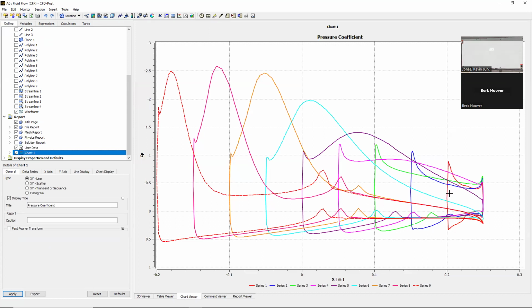They look a little weird. This one out here is the tip. The chord is super tiny, so it's pretty minimal, but it's about what you'd get with a 2D wing. In fact, the outer 3 are pretty close to what you'd get with a 2D wing. But by the time you get to this pink one, you start to see this bulge, and that bulge just goes bigger and bigger and bigger. So all of that is due to that vortex that's stuck on the leading edge. Anyway, so a great way to improve lift.